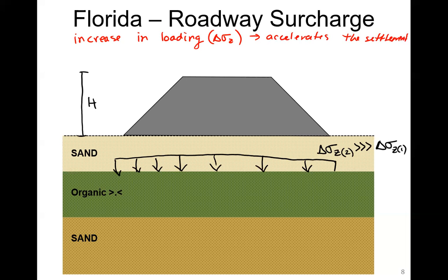So this accelerated settlement is occurring before we put a super expensive roadway on and have the public driving on it, right? So it's kind of nice. And if we need to bring the soil anyway, we can then move this heavy mountain of soil over to the areas that aren't settling, and we can actually carve our original elevations out of that.